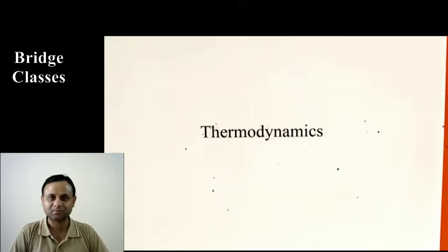You can write it in terms of universal gas constant or gas constant, specific volume or total volume, so you have to be consistent. Based on this law, internal energy, enthalpy, CP, CV are all functions of temperature only. And you also get CP minus CV is R, and dH is CPdT and dU is CVdT.